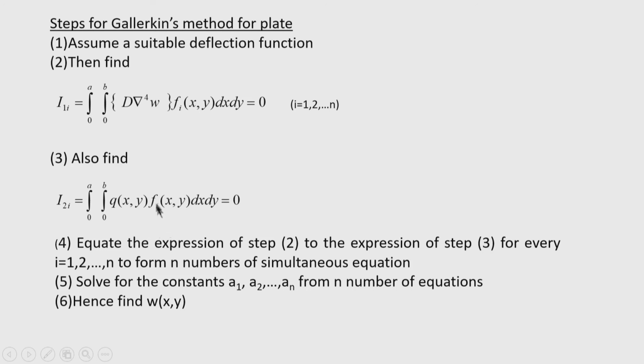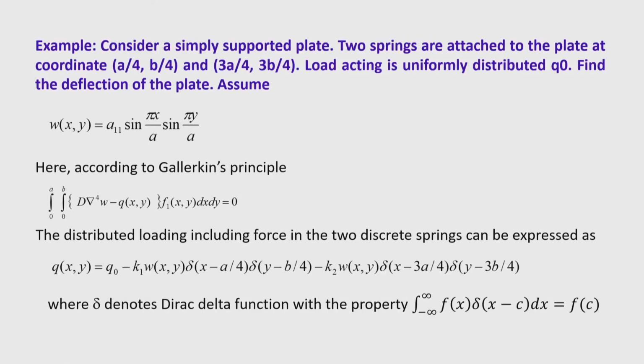Equate the expression of step 2 to the expression of step 3 for every I varying from 1 up to n to form n number of simultaneous equations, and these equations again will be linear equations. Solving these linear equations, we will get the constants a 1, a 2, etcetera, and then the deflected surface can be composed. Let us give one example of a plate with the help of the Galerkin method.